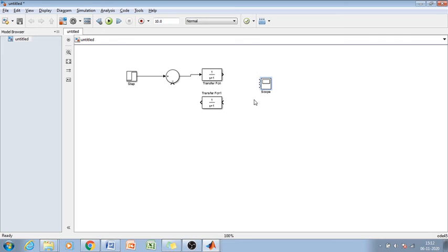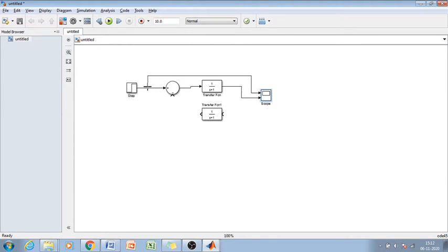So you get 2 axes and 2 ports, and you can connect it easily, one for the input and one for the response. And now we can connect it back to this. That's it. So this is the connection diagram for this first order step input: step input, a summator, a transfer function, a feedback transfer function, and a scope.